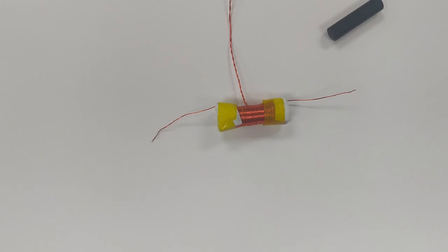It's the AM radio carrier wave frequency, because that's what's carrying our modulated signal. And the way that we're going to pick that up, we're going to tune our components, our capacitor and our inductor, such that the carrier wave frequency corresponds to our resonant frequency.